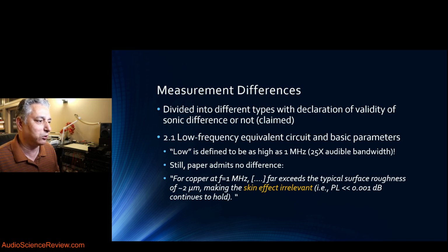Fortunately, he concludes that even if we go up to 1 megahertz, if we measured the losses and things like skin effect, they're at 0.001 dB difference, so therefore this doesn't matter. So it's like, hallelujah, yeah, that's good. And the paper should have really stopped here. There's nothing past this point. If up to 1 megahertz we can't quantify anything being a problem, then we're done on this thing. But this is just the warm-up act.